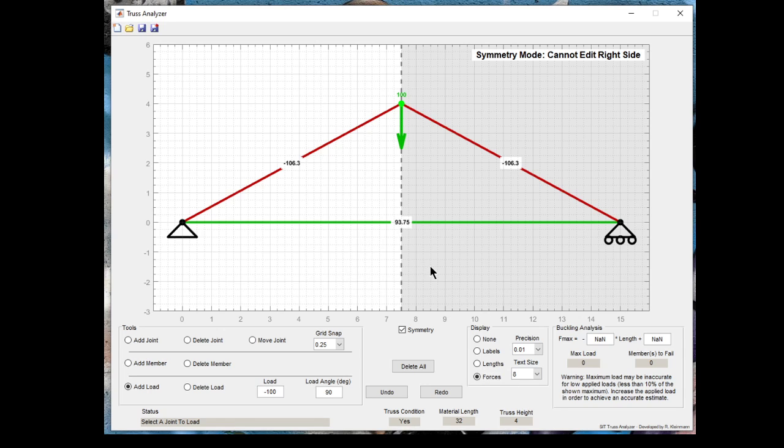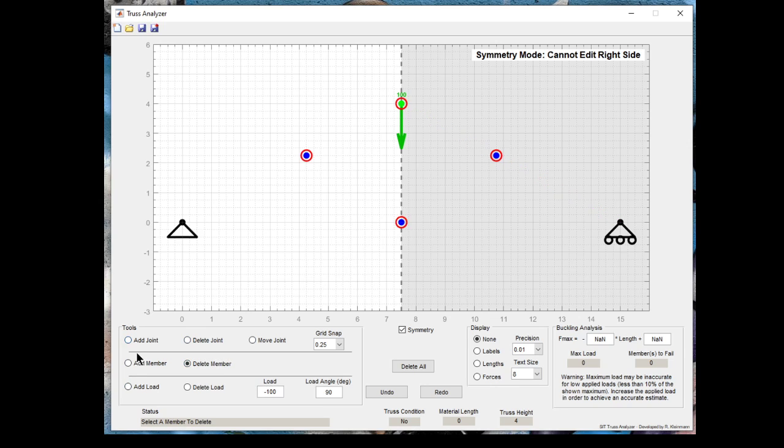And so the point is that now this is an easy place to iterate. So now if I want to, for example, make another truss here and go to the next step, I might say, okay, I'm going to add a joint somewhere over here. I'm going to delete these members, because I actually need to add another joint here. I'm not sure why these aren't deleting. That seems strange to me, but just might as well delete them. Since it's symmetrical, it should be deleting automatically, but whatever.